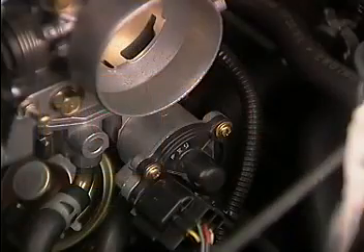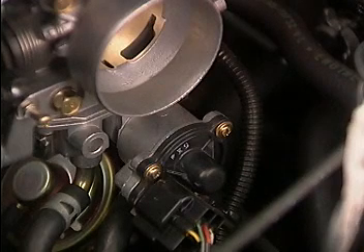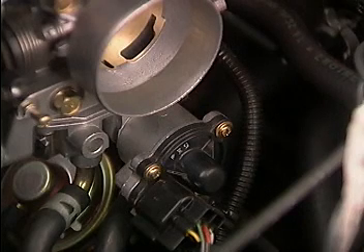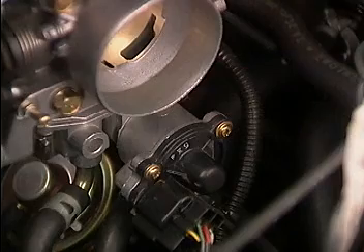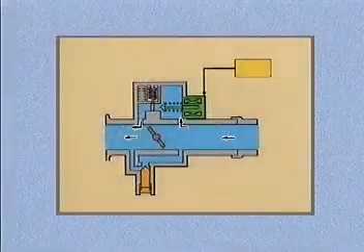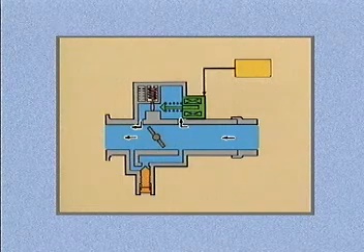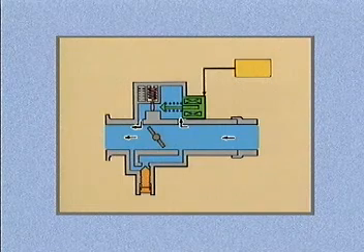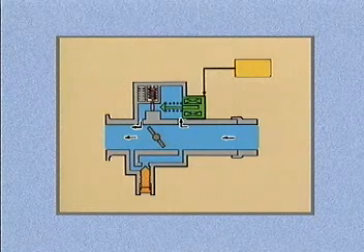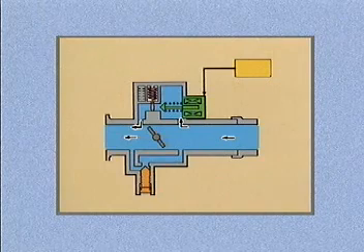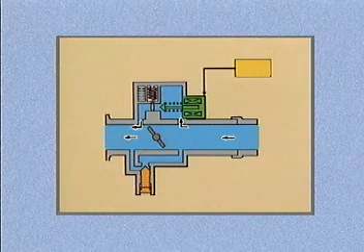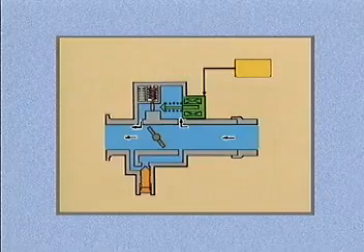The new idle speed control system used on the 1.5 liter and the 1.8 liter engines is the flow-limited control system used on Monteros with 3.5 liter engines. The dedicated wax pellet type fast idle air valve has been eliminated. A stepper motor controlled idle air passage is used for all closed throttle idle air control. A bimetallic flow limiter is used to control the maximum airflow allowed at idle as engine temperature changes.